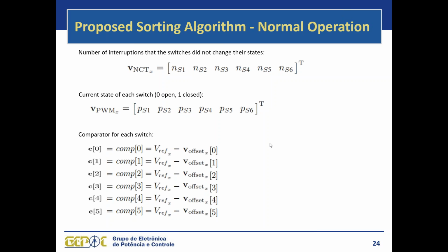Okay, when you have a standard PWM, the switches will switch, let's say, for almost all the interruptions. But when you have the phase disposition, sometimes a given switch will stay for a very long time without changing its status. This very long time is associated to the underflows and period match of the carriers, the interruptions of the PWM carrier in which you calculate your control action and your modulation strategy.